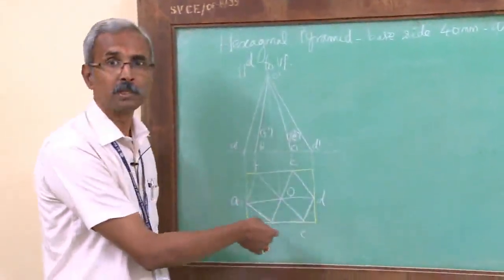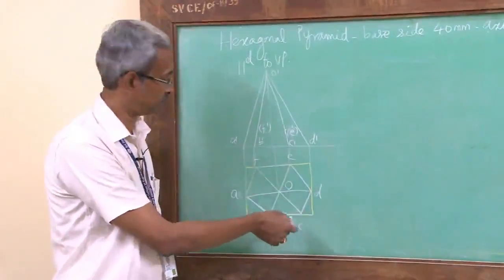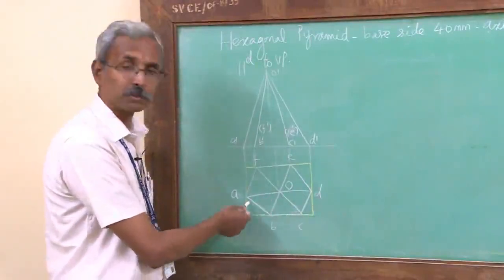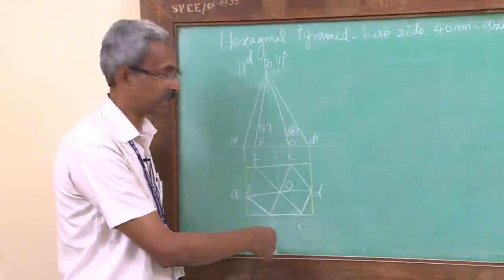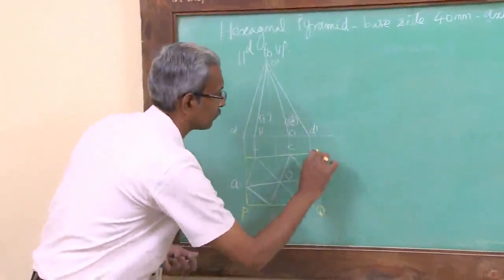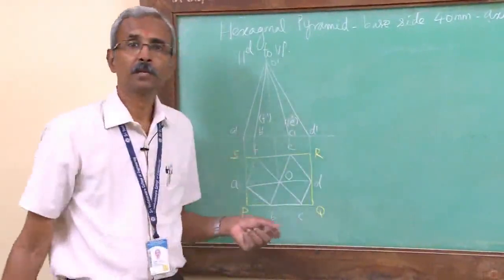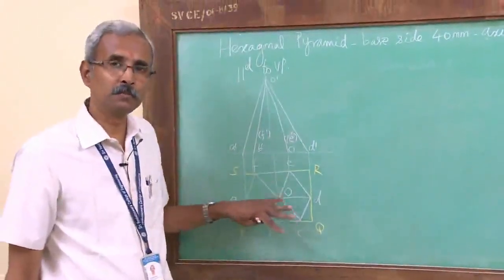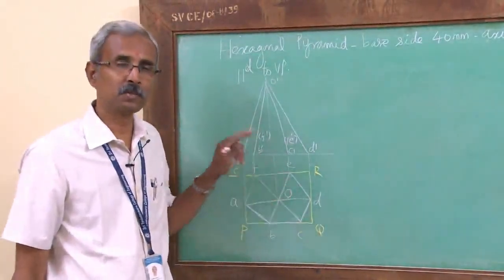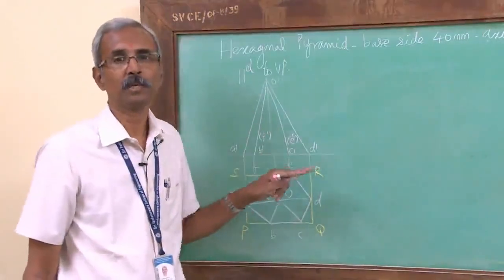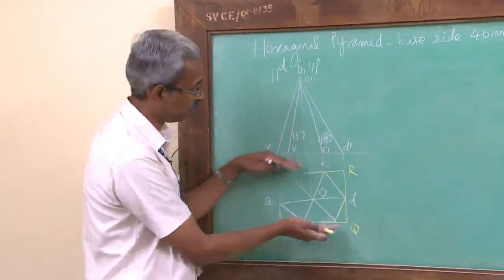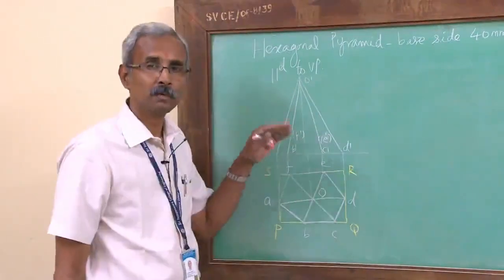So now I have drawn the top view of the hexagon here, and if you look at this, of course a hexagon has non-isometric lines. I have enclosed it in a box. Right? So we need to ensure whether this view meets the given conditions. The condition says two of its base edges are parallel to VP, and if you look at this diagram, FE and BC are the two edges which are parallel to the vertical plane.